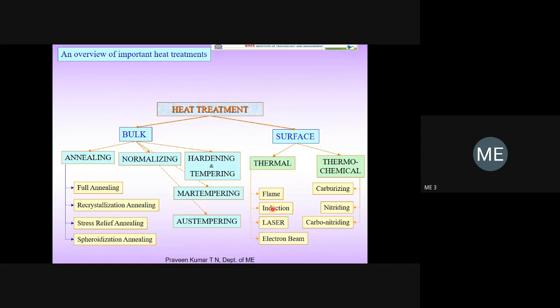Instead of using an oxyacetylene flame, since our purpose is only to heat the surface, we can use electrical sources. The induction principle can be used. The electrical wire is wound, and you supply the current. When current is passed, because of the resistance in the electrical conductor, heat is generated. That heat is used for the induction hardening process. Now when you come to the annealing process, one is recrystallization annealing, that is after recrystallization. The recrystallization is, crystal is nothing but a grain.